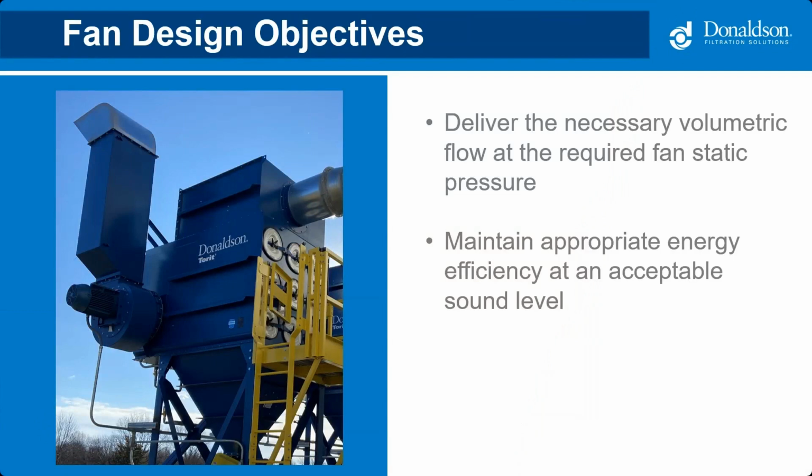And then secondly, the fan you select should be able to deliver the desired static and airflow with an appropriate energy efficiency at an acceptable sound level. For example, non-material handling fans located on the clean side of the collector are going to be more efficient than material handling fans located on the dirty side of the collector.